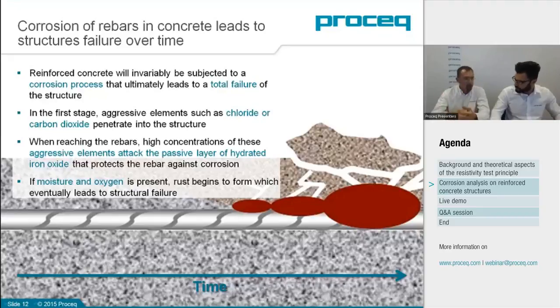That's where cracking or spalling will occur, and then the aggressive agent will have more ease of access to the steel. So it's a sort of accelerated exponential curve, which reminds us that when we see the damage, it's too late. That is the general criteria before going into chemical details.